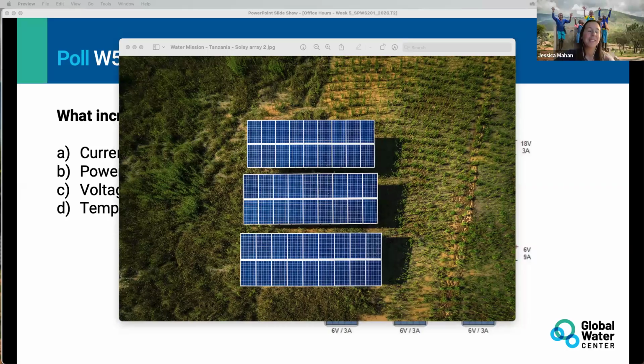Yeah, that's a good point. 15 is a lot, yeah. If you guys can adjust your design to 14 or 16, then you can do it like they've shown here, and just do 7 across or 8 across and have 2 rows, and that would be your string, because it just depends on how you wire them underneath.